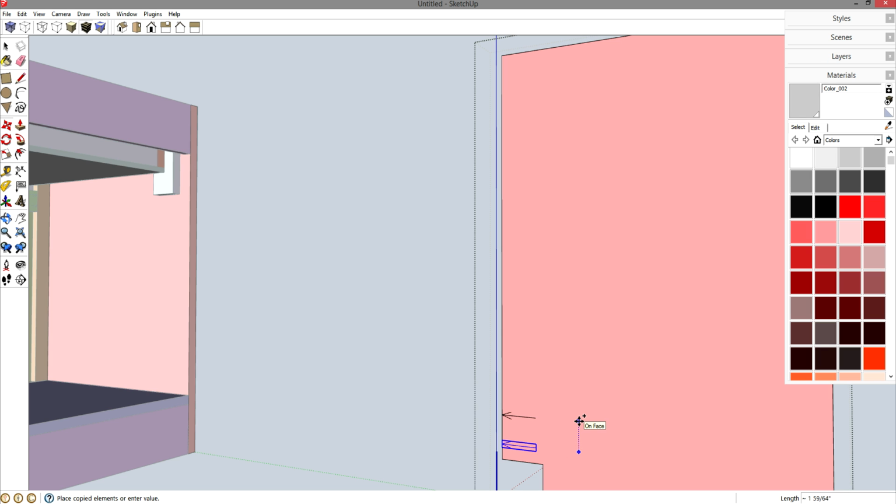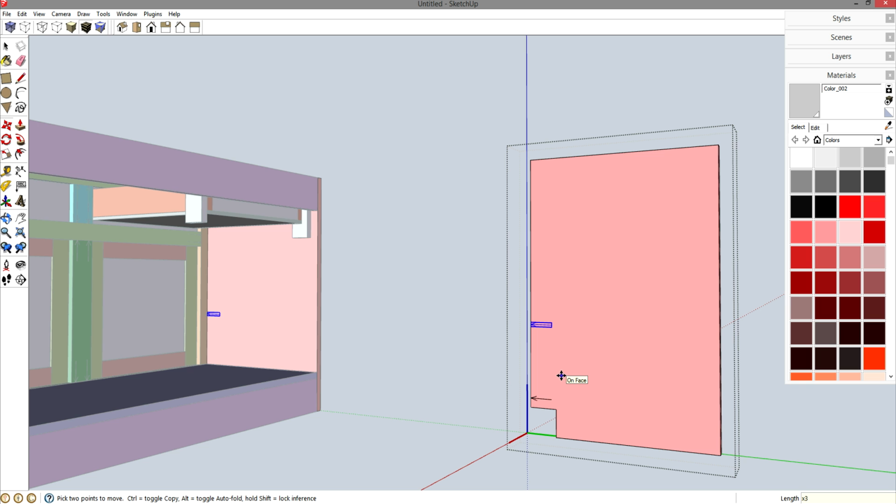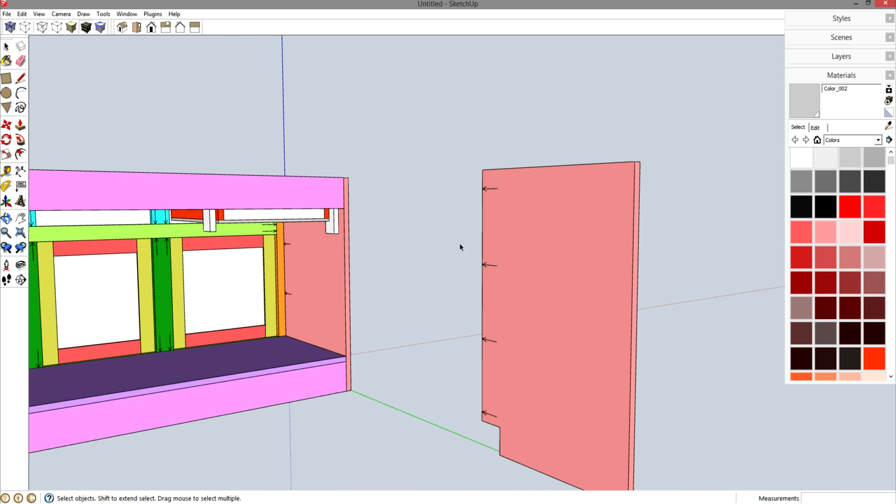Let's go, I don't know, 8, enter, comma, 3. Whoops, what happened? Grab that. M for move, Control brings up copy. Let's go 8, enter. Oh, I pressed comma 3. I need to do X3. X3, enter. And there we go, 1, 2, 3. That's good enough for me.